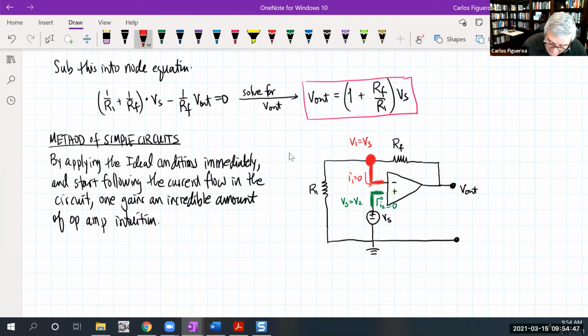So when you're looking at this thing, look how the current is flowing in the circuit. For starters here, look, here's the ground, right? We know this is the ground right here. So if that's the ground, and I have a positive voltage value or node voltage at V1, then of course the current must be going in that direction right there. But wait a minute, there's no current going down that red branch. So that means the current has to be flowing like this. So the current in this branch, which I'm going to call Ix, is the same current in that branch.